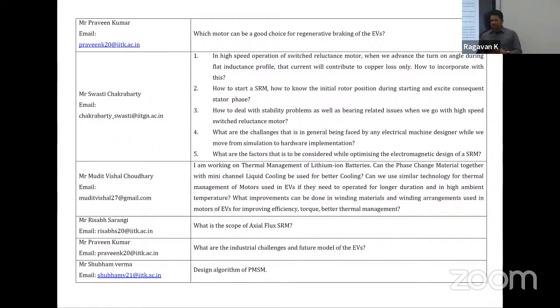So optimizing electromagnetic design, I gave you the full download on the design parameters for the SRM. Your primary objective is going to be looking at your saturation level for your motor and how much heat you're going to generate. Torque ripple and acoustic noise are big issues that you always have to deal with. If they know SRM, the first question they will ask you is, how noisy is it? So be prepared to answer that question.